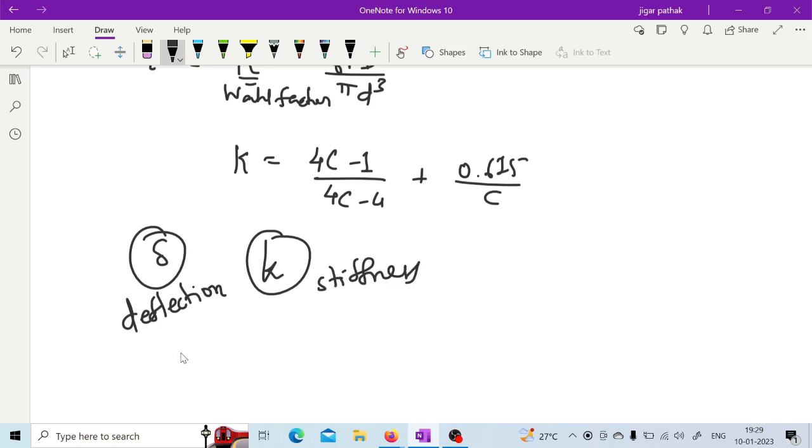So yes, that Wall factor and Ks into Kc are the same, you can consider. But this is different actually, means it has been calculated based on some experiment, and maybe there's some empirical relation he has found. So it is not exactly same, but you can consider it as that particular effect of this curvature as well as effect of this direct shear stress. Okay, so Wall factor is derived by considering both curvature and the direct shear stress. Yes, by considering both.